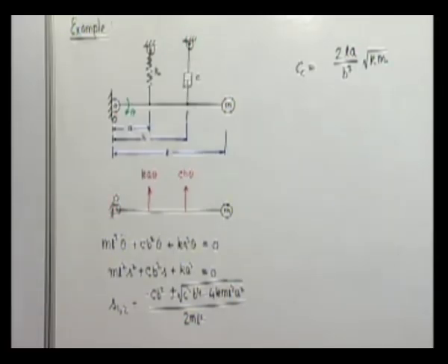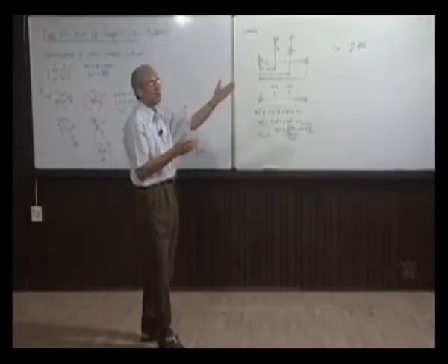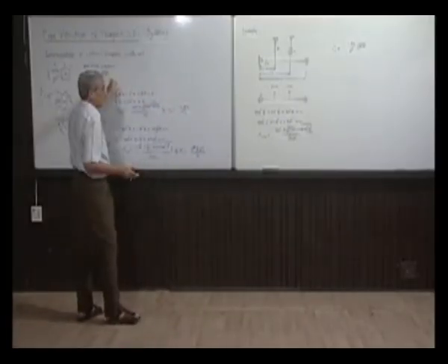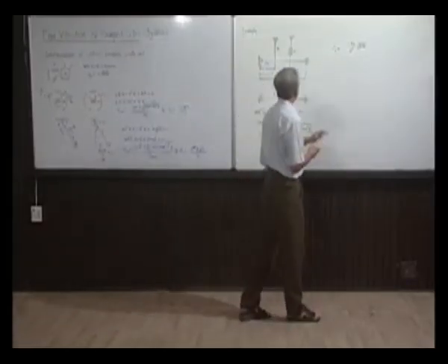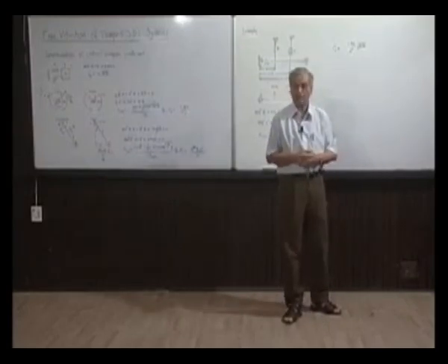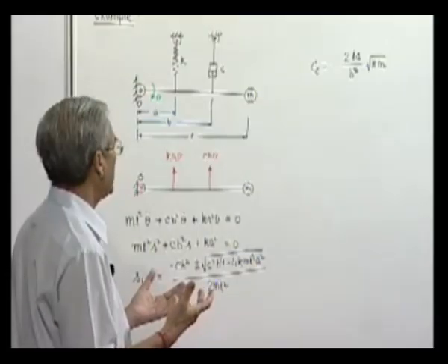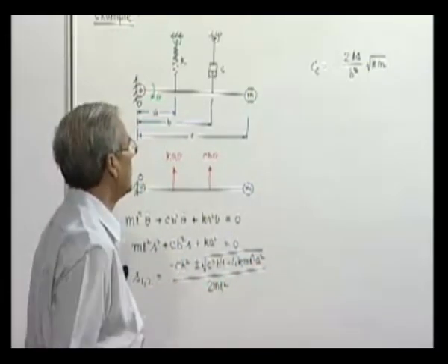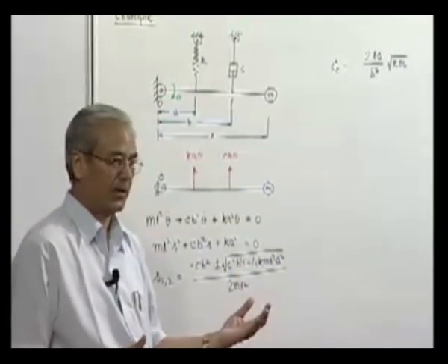So therefore, we have to keep this in mind that for each and every individual configuration or system, there exists a different expression for the damping coefficient. So, you should never consider that the critical value of the damping coefficient is always given by this. Each time it has to be found out. So, as for the application of the critical damping coefficient, we have already mentioned that the practical applications will be in all such cases where you do not want the system to cross the equilibrium position, or rather approach the equilibrium position with negligible velocity.